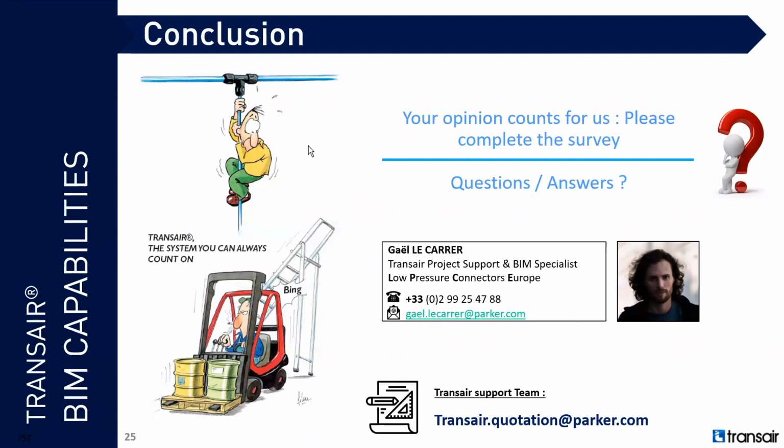Regarding compressed air as a fluid inside Revit: no, naturally it does not have it. It only has the classification, but there are no types inside it. So you need to create your own type of system of fluid. We do add them inside the template, but if you need some more specific ones, you just need to create them.